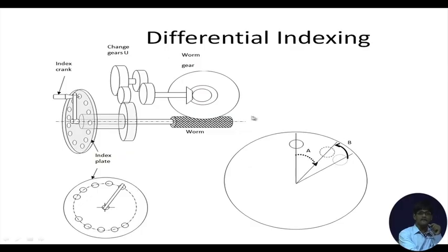Coming to the figure now, let's see how this is physically implemented. Physically, we see that there is an addition of a gearbox. Now all those discussions that we had about gears and gearboxes, etc., will now become quite relevant. Since I want to rotate this index plate, I am tapping motion from the worm gear, putting in a gearbox, with some ratio, I do not know that. I will find out what should be its ratio, and I am simply rotating the index plate backwards or forwards, whichever be the case.